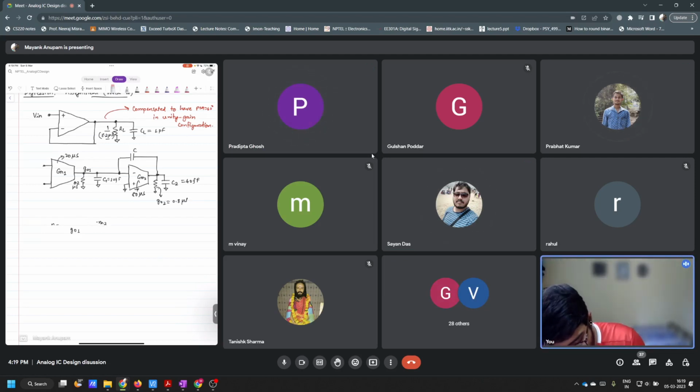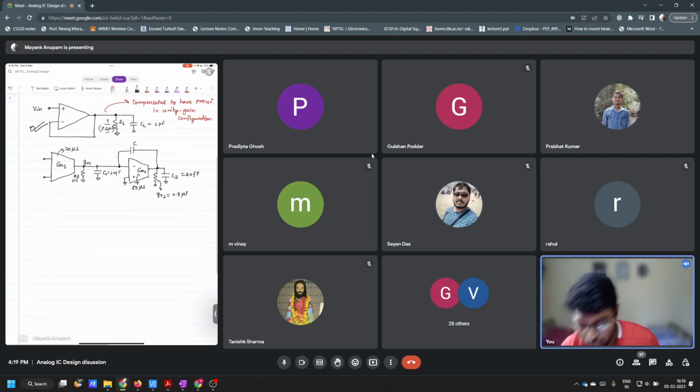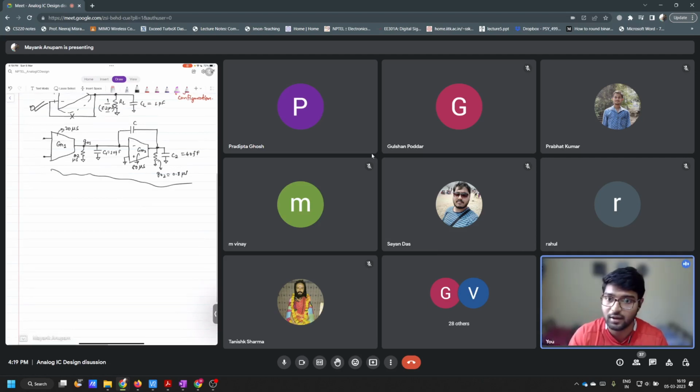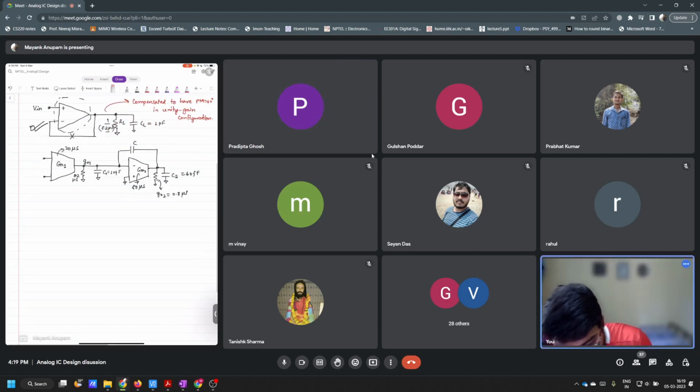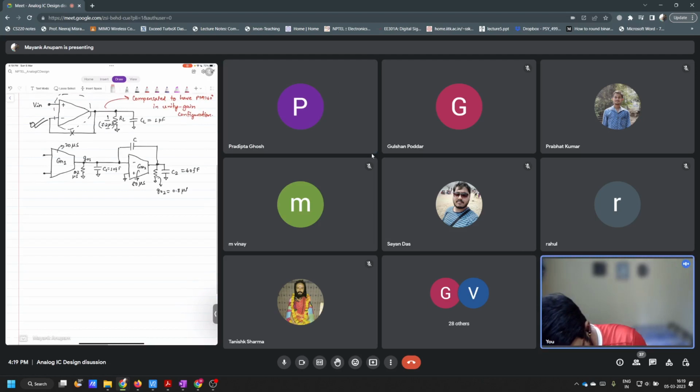You see, this is the one which we are considering, right? So we have to open the loop for this one in this manner. When we open the loop, this op amp inside here is replaced by its model here, so that we consider it as a whole. So here we will have to consider RL while calculating DC gain. So what will be the picture in DC gain?